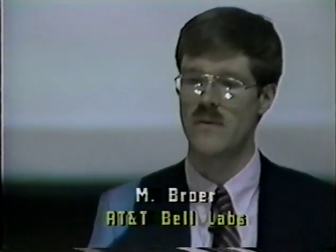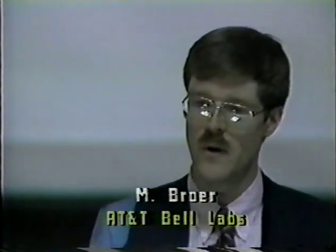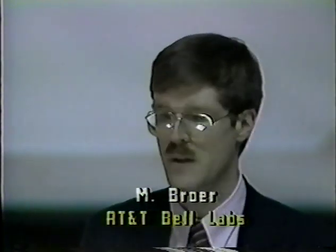What we have done is concentrate in the first 4 weeks of the experiment on trying to reproduce the Pons-Fleischmann results, focusing on palladium materials only at this point in time. We have typically used palladium wires a little over 1 millimeter in diameter by about 9 centimeters long. One of these wires was cold drawn only, the other one was cold drawn and annealed. The larger rod, which we cast ourselves in boron nitride crucibles, was subsequently cold drawn to reduce its diameter, and after that annealed at around 900 degrees centigrade for 1 hour in nitrogen.